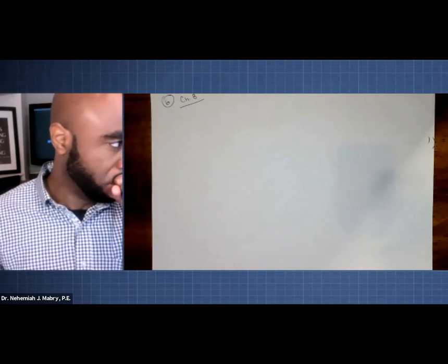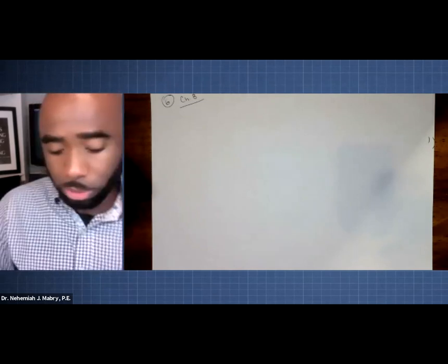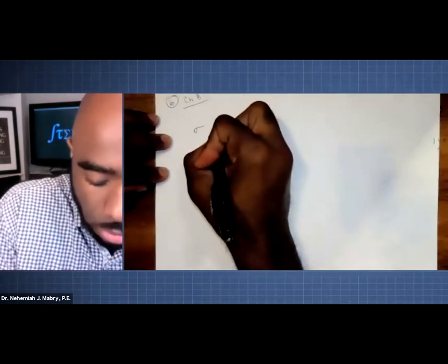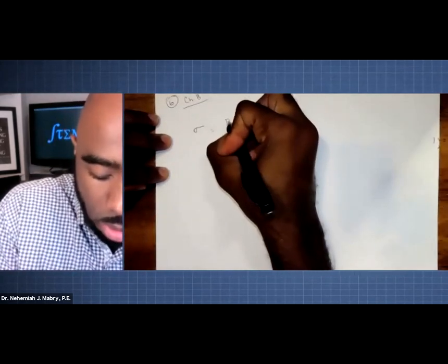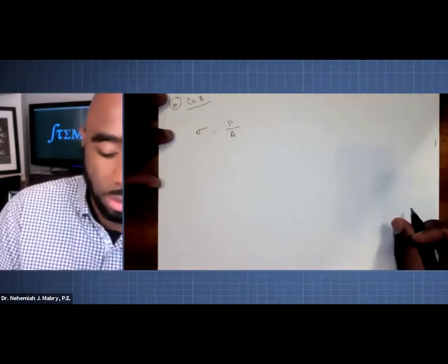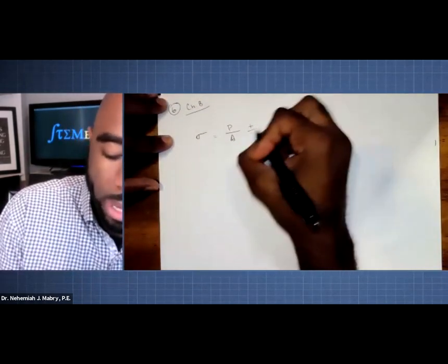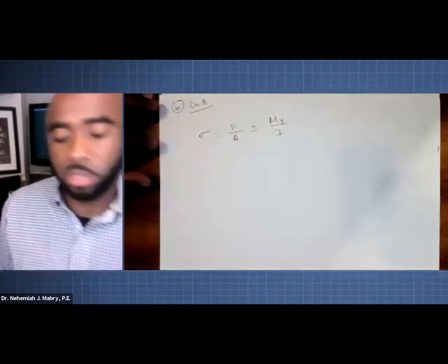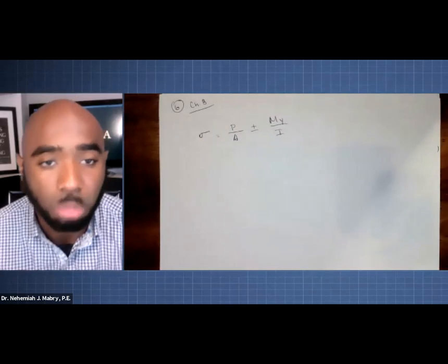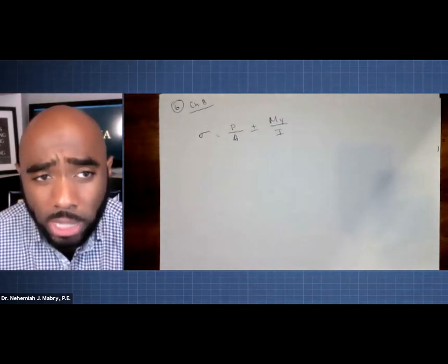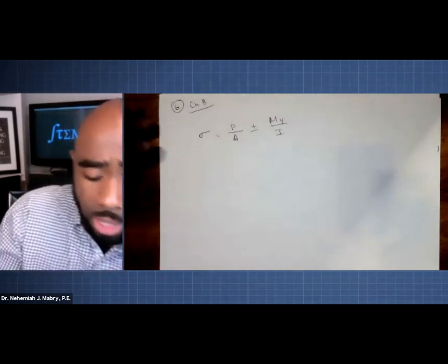Just a few days ago, we talked about this one. So your stress is basically equal to a combination of your axial stress plus or minus your flexural stress. This was quite straightforward to explain.